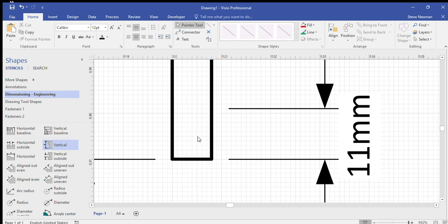Here's our 11. Now, our central shaft should really have a centre line drawn on it, because I like measuring off the centre. For some things you can't measure off the centre, but a lot of the time you'll be able to. Let's draw a centre line. Now I can just count this up. I know it's 8 mil, so 1, 2, 3, 4. There's our middle. Draw a little line.